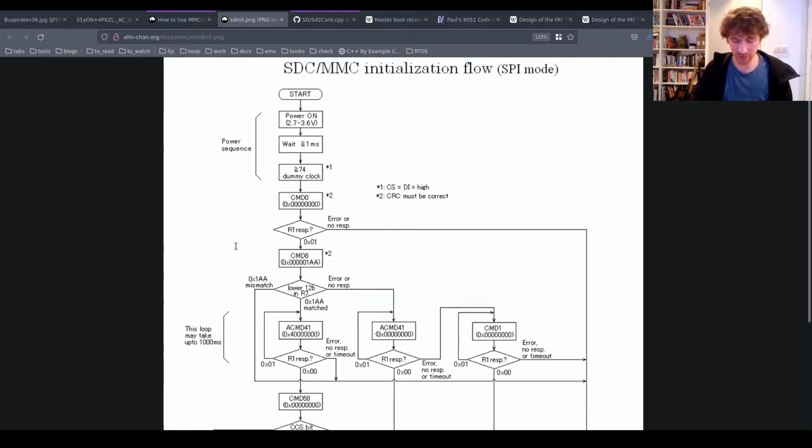In order for us to send command 0, which is software reset, we first need to enable chip select, which is going to be a manual thing. And what I like to do is write the corresponding disable immediately so that I don't forget to do it. That's like if you're working in a language where you have to control your memory and you do a malloc, immediately writing the free and making sure that you actually do that somewhere. Or in some of these newer languages where you can do defer and stuff like that. So that is basically the equivalent of this.